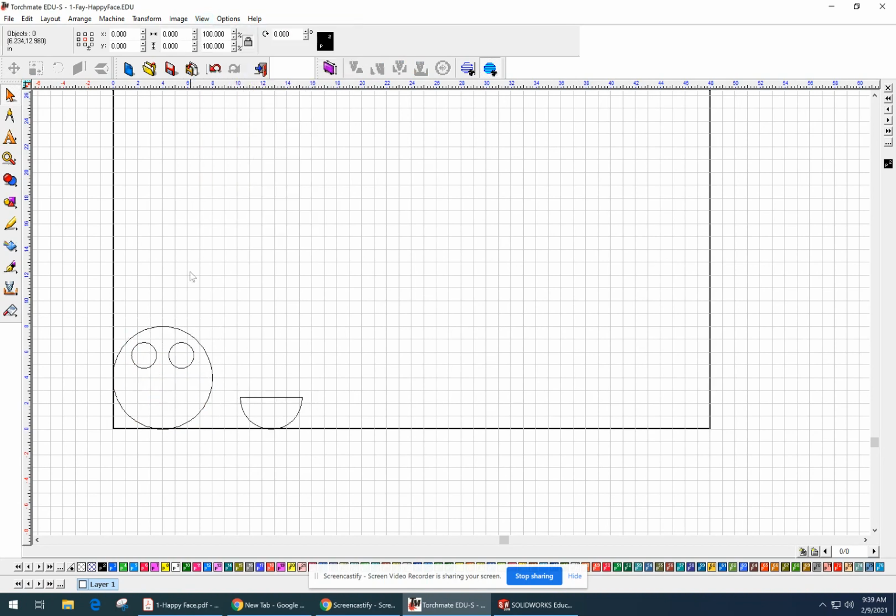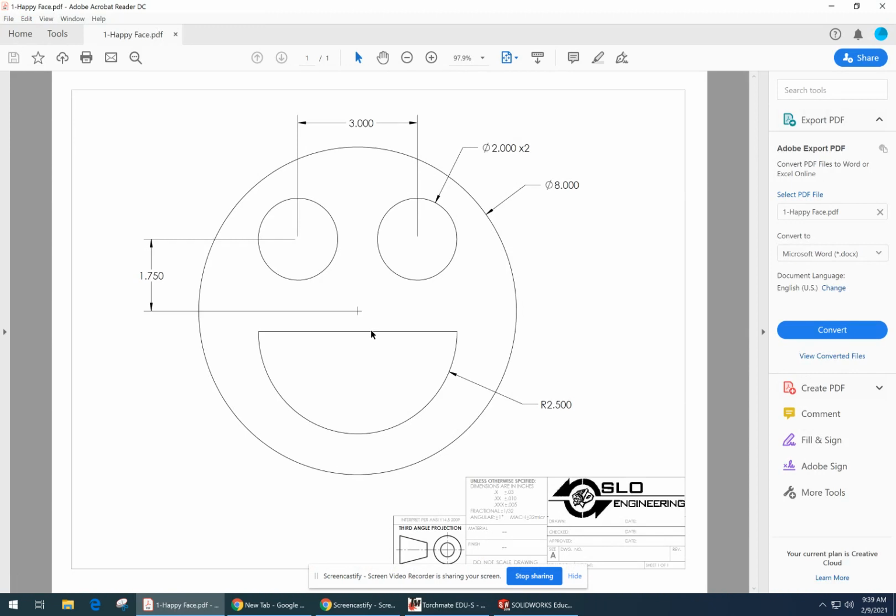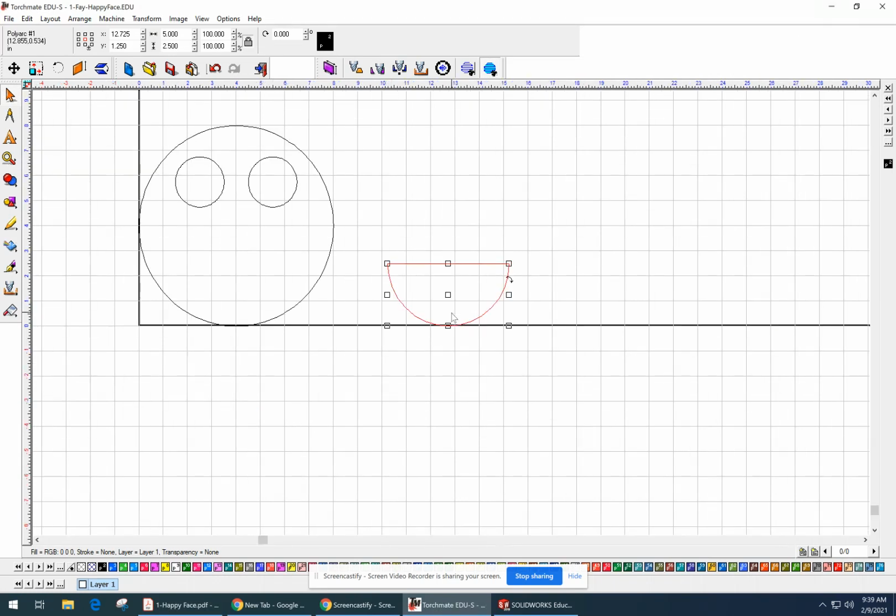Okay, let's turn off the show fill and let's take care of the mouth. I did notice on the plan that the mouth, unfortunately, I left off this dimension, but it's just a 1/2 inch. So a 1/2 inch below the center is where that one should go. So what we're going to do there is I want to grab this location right here. So that would be the top center nub. And I'm going to make the X 4. That centers it right to left because everything should be on a 4 inch there, right?